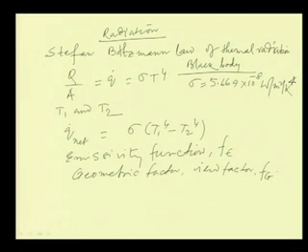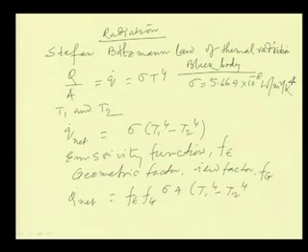So, the net exchange between two bodies depends upon a factor called the view factor or geometric factor, and therefore, the net exchange between any two bodies could be written as F epsilon, the emissivity function, into the geometric function, into sigma, into area, into T1 to the power 4 minus T2 to the power 4. This is derived from the Stefan-Boltzmann law of thermal radiation.